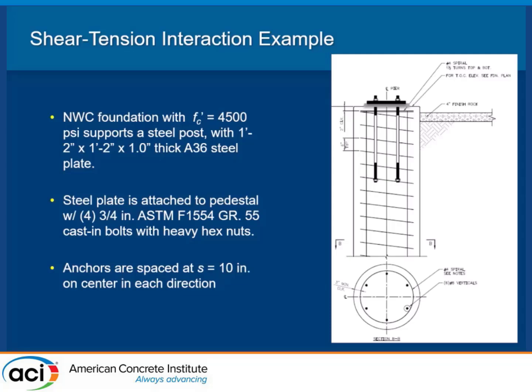making the calc? I know if I'm this far deep and I have to go this far deep, or if I'm maybe further up here and I could just go a little further down, why don't I just use this as anchorage reinforcement? It's just sitting there waiting. Why even do the check, right? But you can do the check, but remember your H effective is going to climb way up here, and so all your calcs are going to be off as if that headed anchor was here.